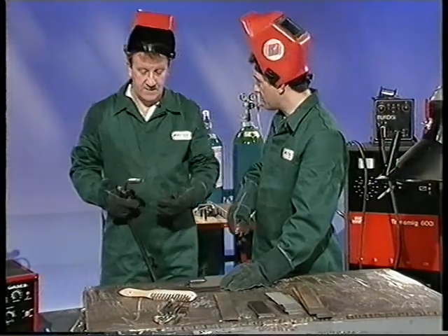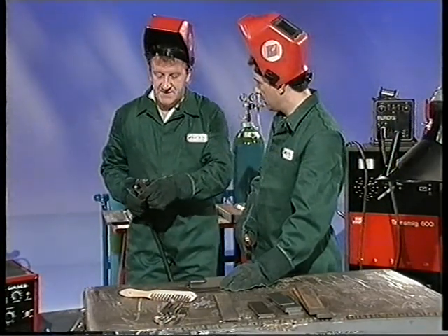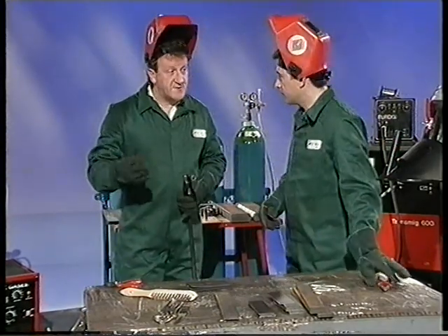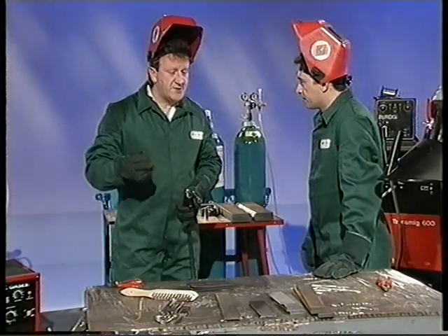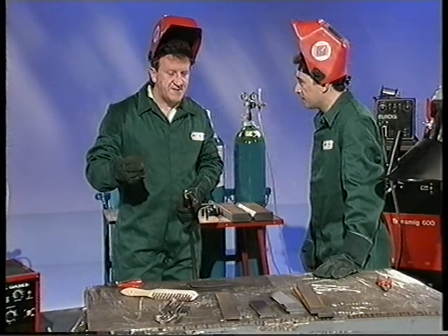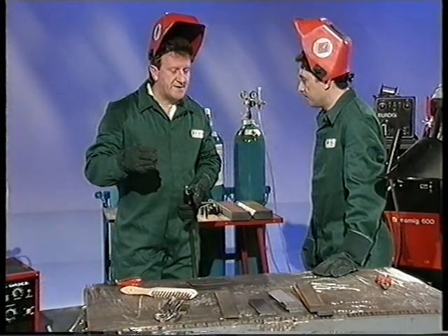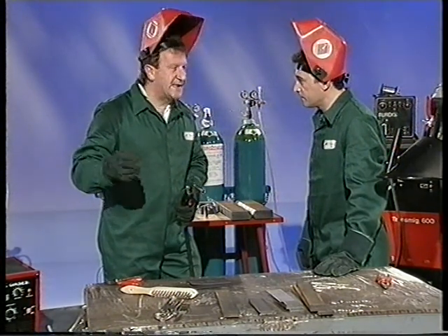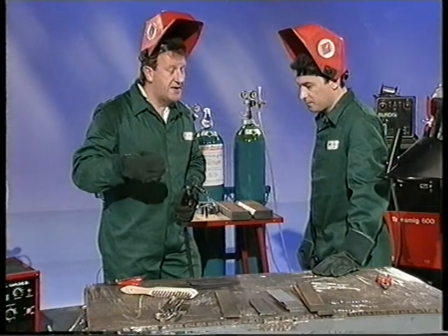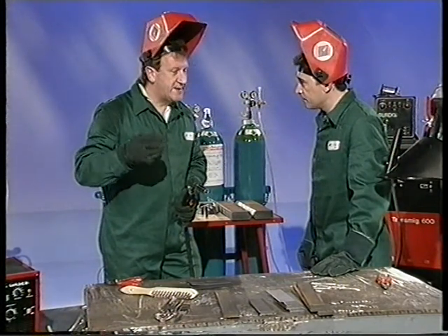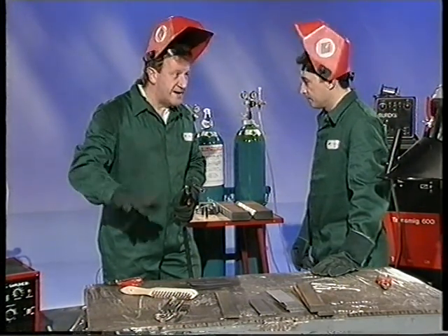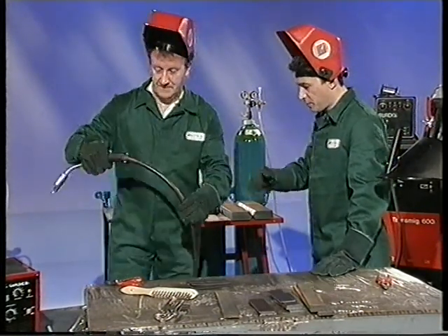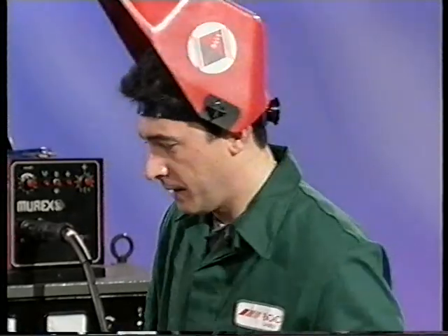Is this the best way to weld thin material, do you think? It's certainly the most commonly used way, but there are advantages in using synergic pulse machines for thin material. Synergic pulse machines also have big advantages in positional welding. There are some beliefs that the dip transfer in positional welding can lead to lack of fusion problems. To overcome this, if you use synergic pulse where you're simulating spray transfer but at far lower amperage than spray transfer can take place, there are benefits as far as fusion goes. Okay, perhaps we can see that if we rig for that next then, Mel.